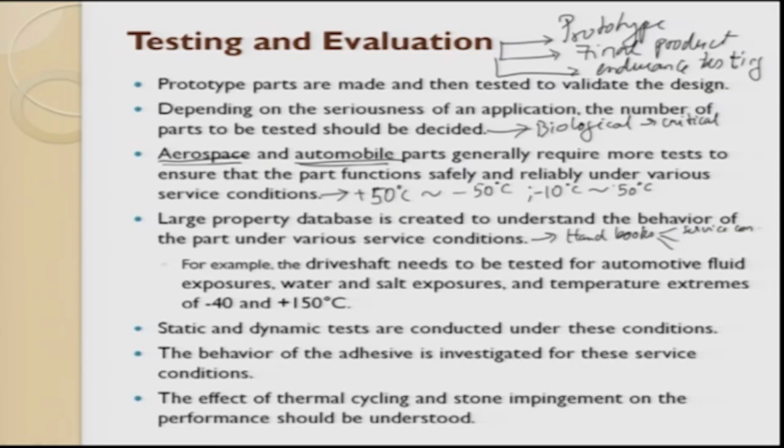We recently worked on a project wherein we were trying to make gaskets. Gaskets for two mating surfaces, and we made perfect castings at room temperature. But we did not realize that when they went for vacuum testing, these gaskets would fail miserably. So at room temperature it worked perfectly. When it went for vacuum, that is a service condition, all these gaskets failed. So service condition is very important, and today you get handbooks which talk about that.